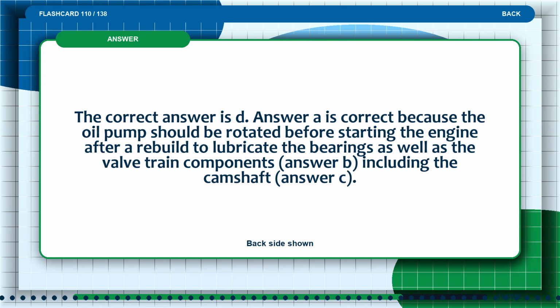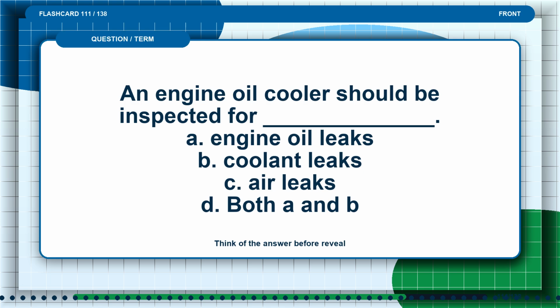The correct answer is D. Answer A is correct because the oil pump should be rotated before starting the engine after a rebuild to lubricate the bearings as well as the valve train components. Answer B is correct, including the camshaft. Answer C is correct.